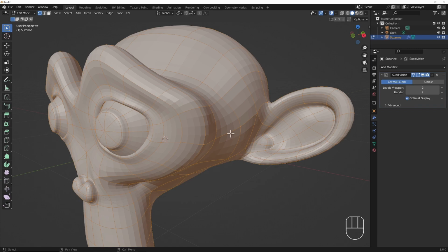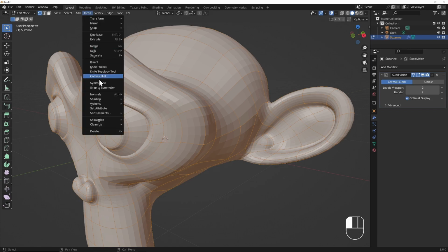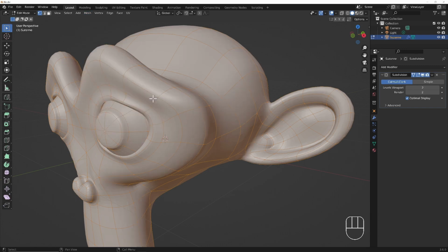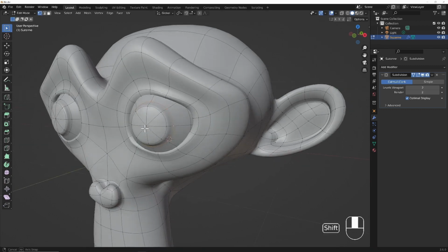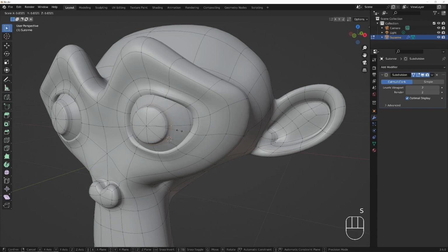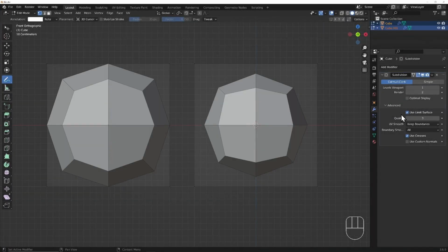This object is still flat shaded. I'm going to switch this to smooth, and now we can see how this modifier can really help with the final result. The original mesh will now act as a cage, and as we move vertices around, the subdivided mesh will dynamically update, almost as if there was a proportional fall-off applied. There are some advanced settings which, by default, are enabled to give the most optimal results, and they can be adjusted for more specific uses should you need them.